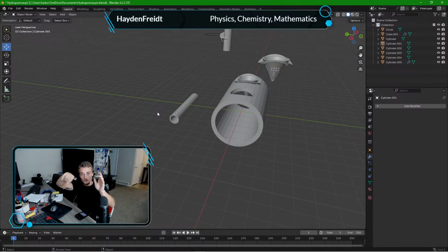It's a 90 degrees, it swings around. How far this way am I gonna end up? So talking about my X, you know, you have your Y, you have your X, and then your hypotenuse, things like this. So we're just looking at the X. And it's 5 inches for each gutter elbow. So when you're making that sweep, you're subtracting 10 inches because you know that you're gonna have 5 inches accounted here for one elbow, 5 inches accounted here for the other elbow.